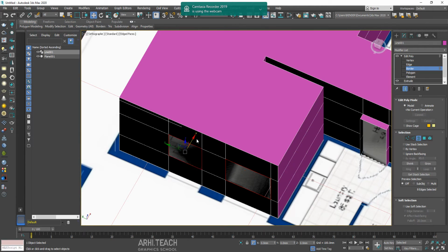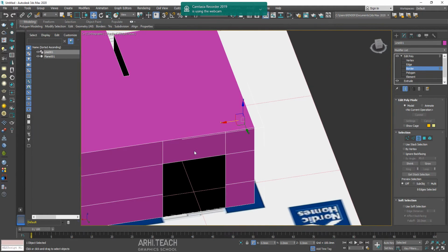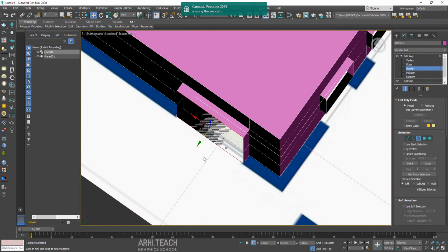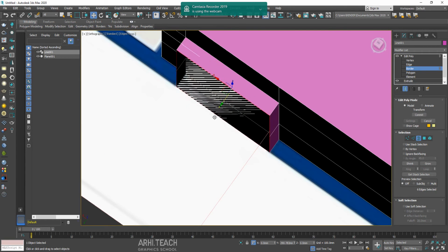Here we extrude the window opening at once. Just a displacement with the held Shift. Here we have it as well. Besides, we see the thickness on the plan. It also helps us. Well, we have chosen the doorway.